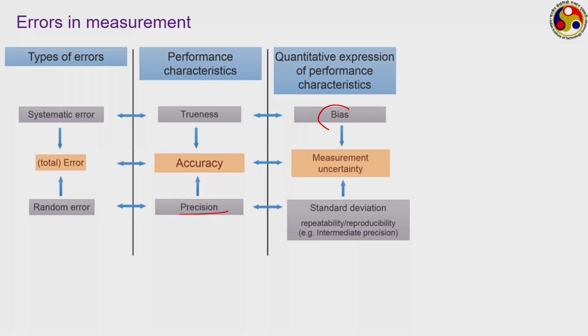Like using the same instrument, if we want to measure the same variable several times, because of the presence of random errors, we may get different values. So, random errors basically affect what we call the precision. That is, because of the presence of random errors, the different observations of the same quantity may get scattered around some kind of mean, thereby affecting the precision of the final output. That is why random errors are also referred to as precision errors.